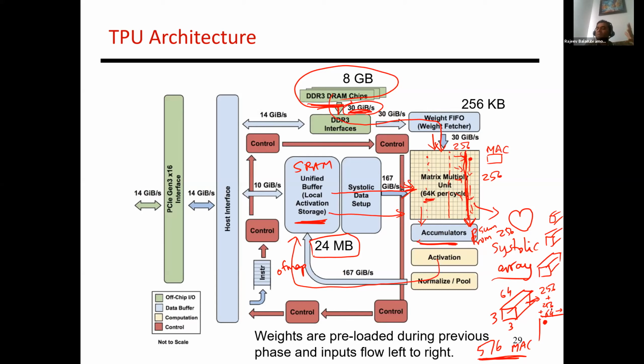Okay, so hopefully this example gives you some insight on how weights are being reused, and how input activations or input feature maps are being reused. This also gives you some insight on how the computation is broken up into multiple stages. Some stages have very high efficiency, other stages have less efficiency, right? If I didn't have 256 filters, I wouldn't have kept all the columns busy either. So if you're not doing 256 filters, again, your utilization goes down.